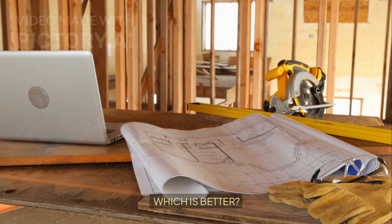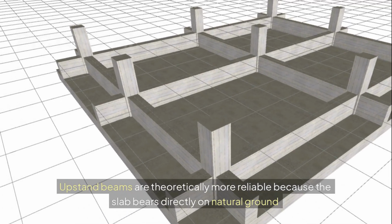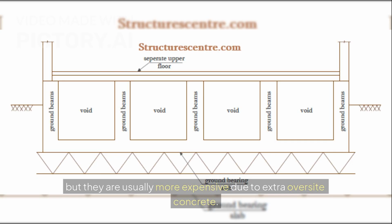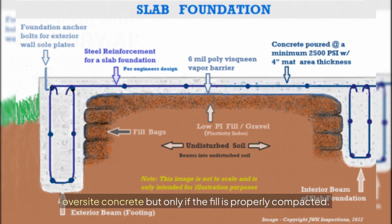Which is better? Upstand beams are theoretically more reliable because the slab bears directly on natural ground, but they are usually more expensive due to extra oversite concrete. Downstand beams, on the other hand, can be more economical because the raft slab also serves as the oversite concrete, but only if the fill is properly compacted.